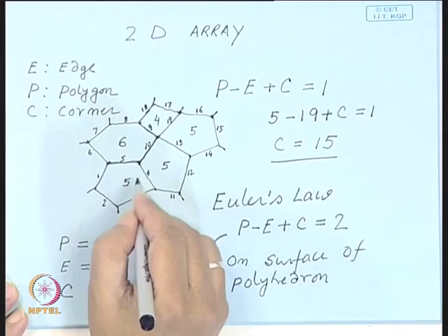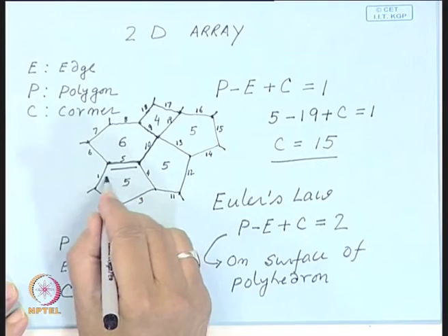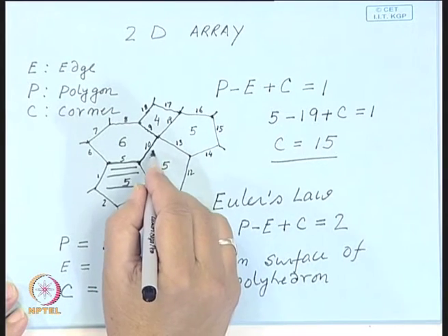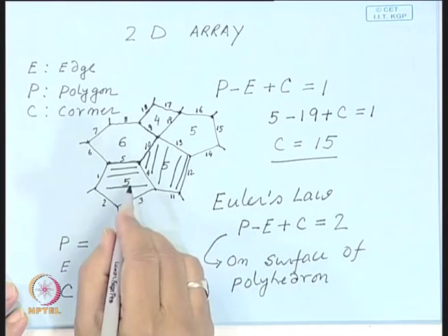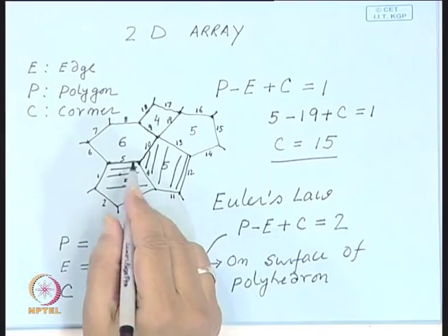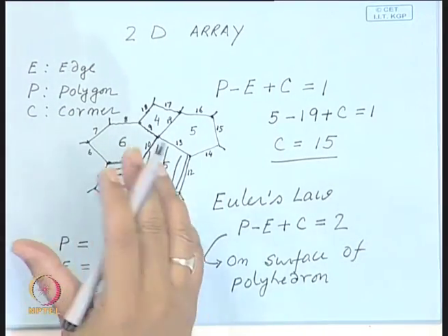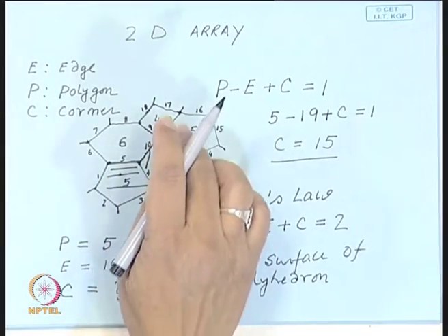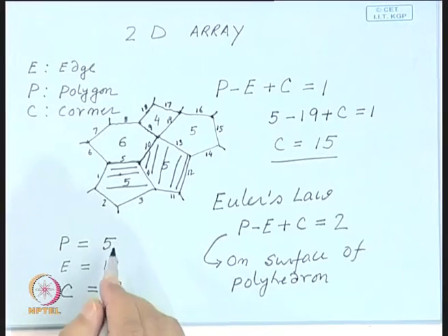They meet each other. So, this will have one crystal arrangement, say here these planes are arranged like this. So, here possibly the planes are arranged in a different way. So, if you move from one grain to another, the periodic array, the crystal structure is still the same, but its orientation is different. The same planes are oriented differently.